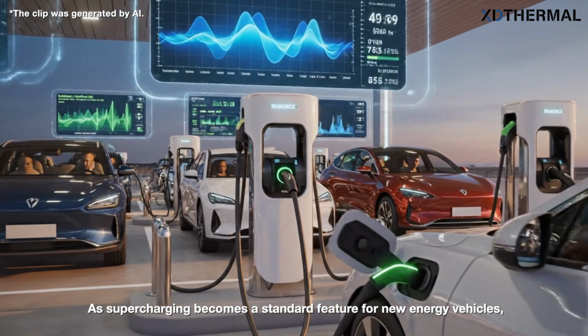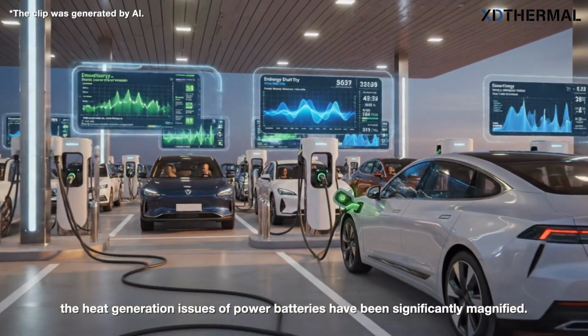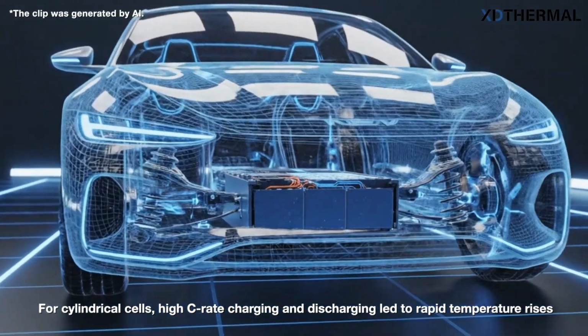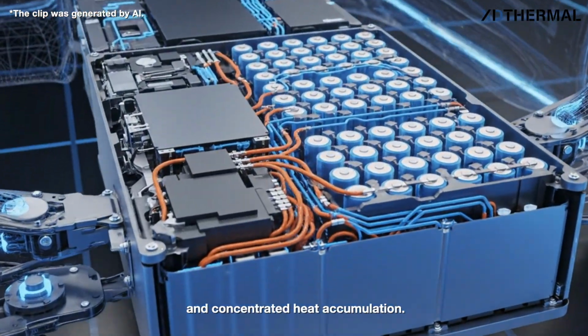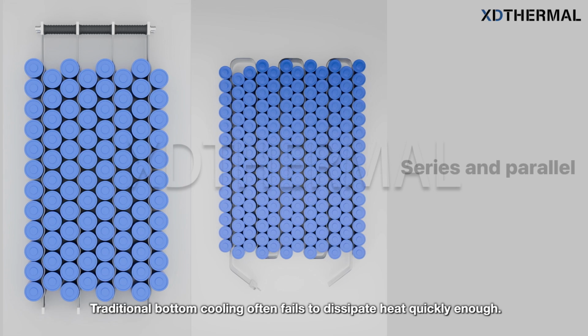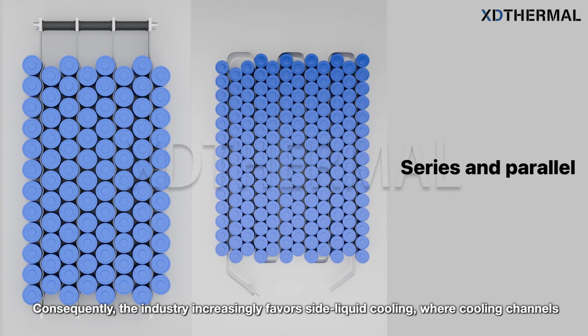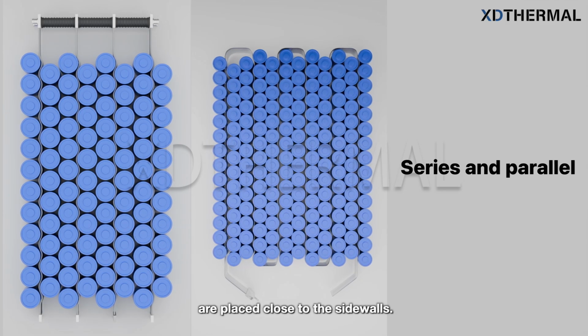As supercharging becomes a standard feature for new energy vehicles, the heat generation issues of power batteries have been significantly magnified. For cylindrical cells, high C-rate charging and discharging lead to rapid temperature rises and concentrated heat accumulation. Traditional bottom cooling often fails to dissipate heat quickly enough. Consequently, the industry increasingly favors side liquid cooling, where cooling channels are placed close to the sidewalls.